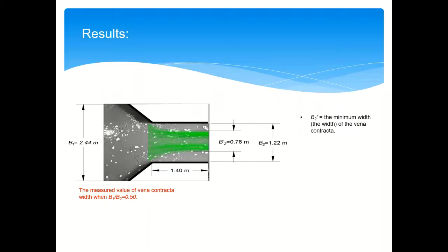I cannot give you any number for that. I can see a bag full of pieces of paper, because for the LSPIV we need a good coverage of paper pieces on the water surface. So we seeded the flume as much as possible to get a good sequence of video with a good coverage of paper pieces on the water surface.